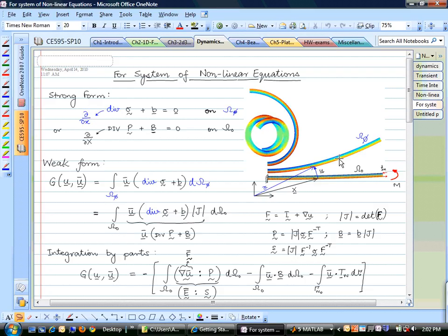So in this case, again, what you have are multiple different steps of the nonlinear analysis, in the sense that if you apply a small moment, your equilibrium configuration will be this. From here, if you apply additional moment, your equilibrium configuration will be this, and so on. So if you choose this equilibrium equation defined on that deformed configuration, you can write the same equation back on the original configuration in a little different way. So what you should note here is that this div sigma plus b, this is our favorite equation, but